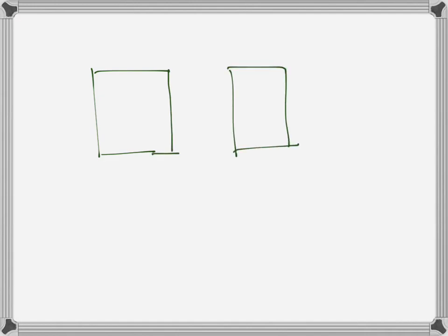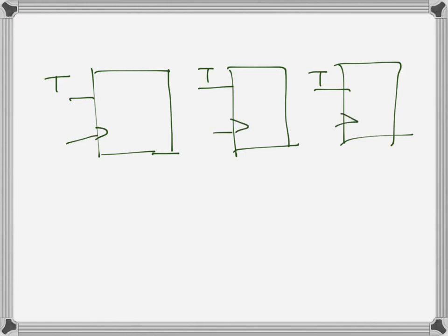We are going to demonstrate frequency division using an asynchronous counter. So let's say we will deal with a 3-bit counter. We have 3 flip-flops, 3 T flip-flops here, and they are rising edge clocked, as the sign shows, and this is Q0, Q1, Q2. Let's mark it like that.